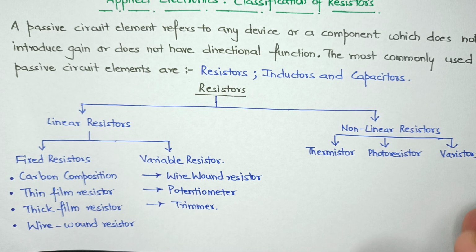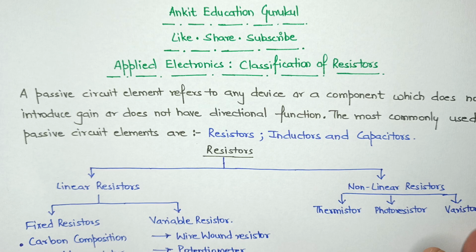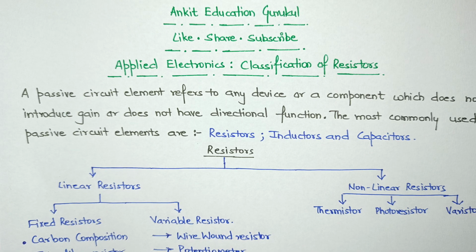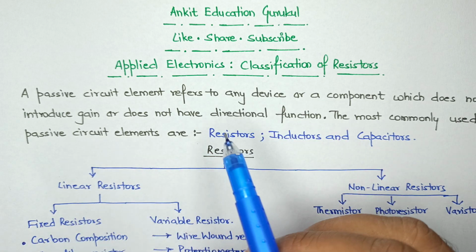Now as far as the resistor specifications are concerned, resistors are specified in terms of their resistance values, tolerance, power rating, and thermal stability. By tolerance, I mean the allowed variation permitted in the nominal or marked value of the resistor. It means that the actual value of the resistor may be either greater or smaller than the indicated value by a factor of a specified tolerance.